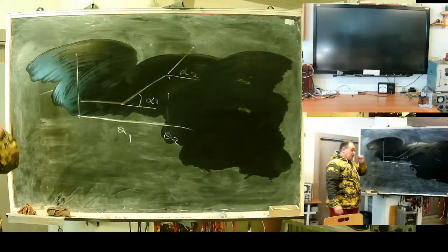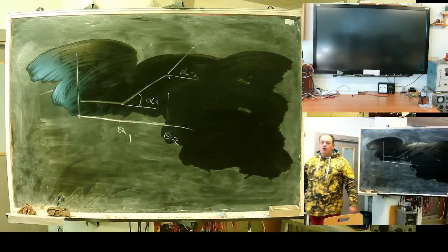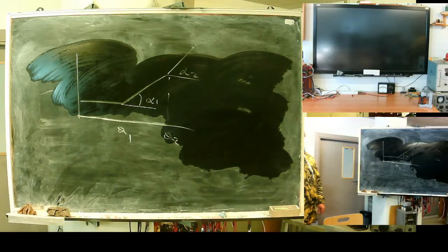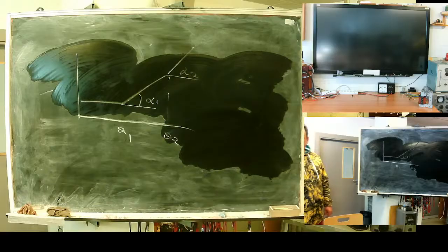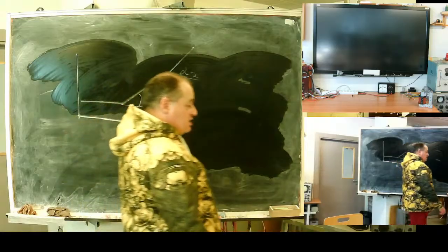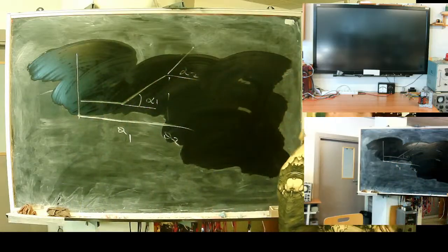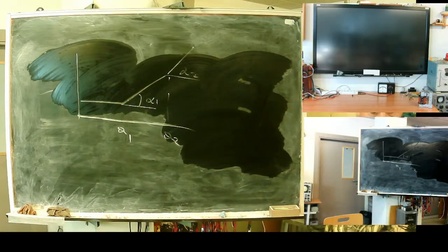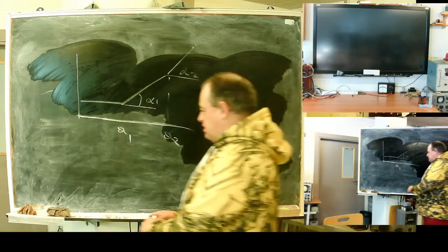It's a correction chart, a linear approximation of the error characteristic of your current transformer. When high precision is required, calibration should be done in 3 points, and the correction or de-erroring characteristic should be put inside.